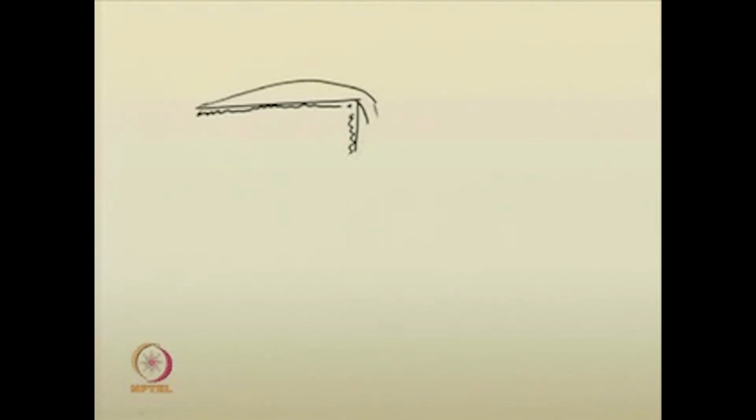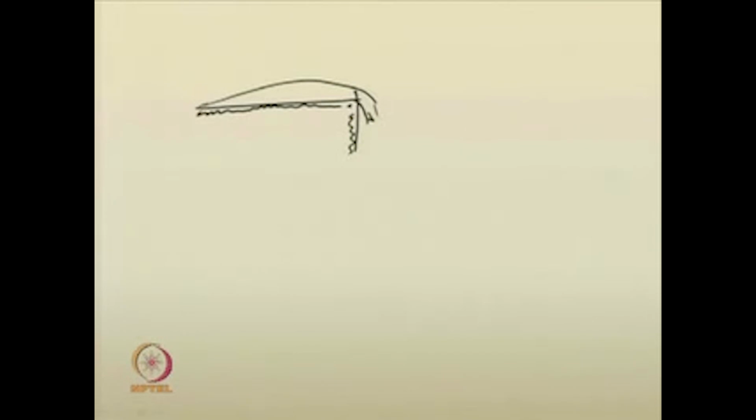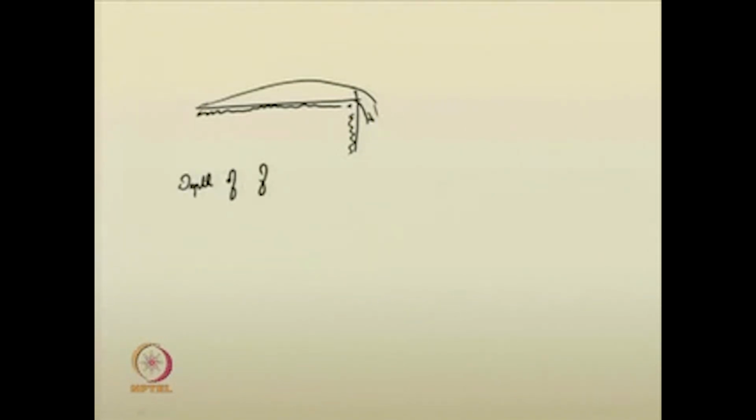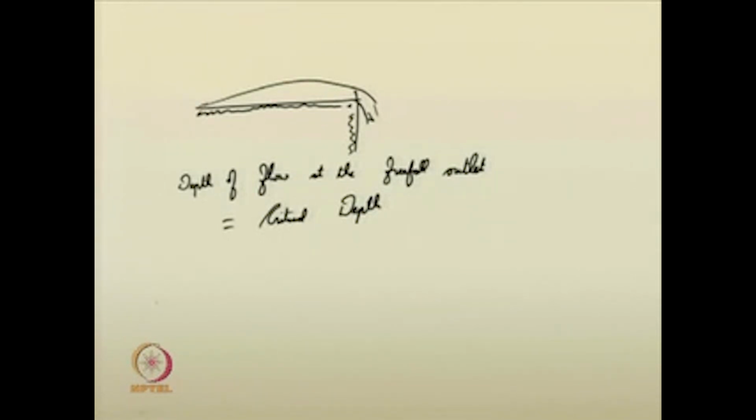So, in this case, what will be the depth of flow at the free fall outlet? This should be equal to the critical depth in the flow. So, if that is clear to you, then